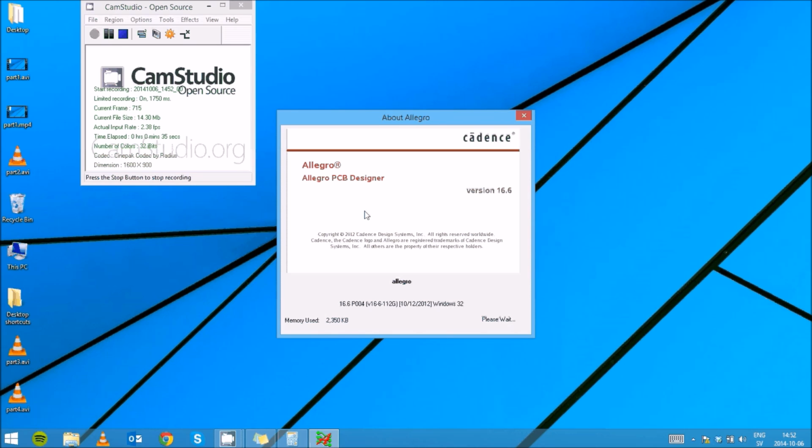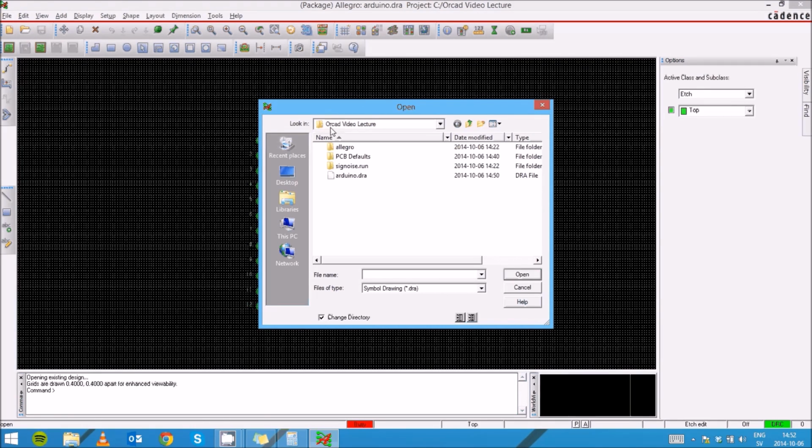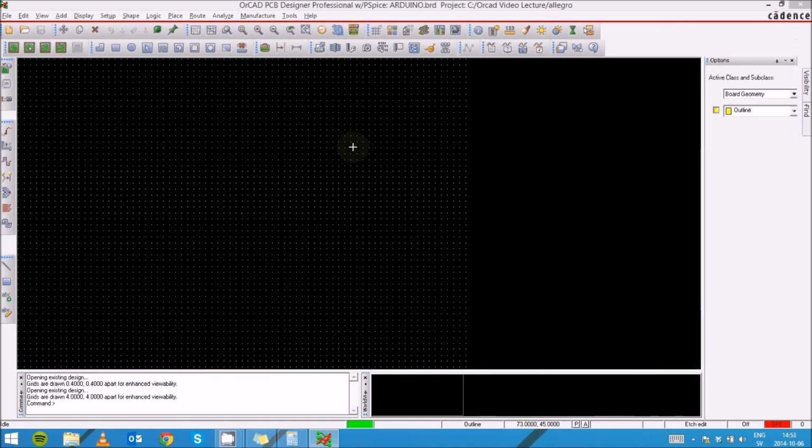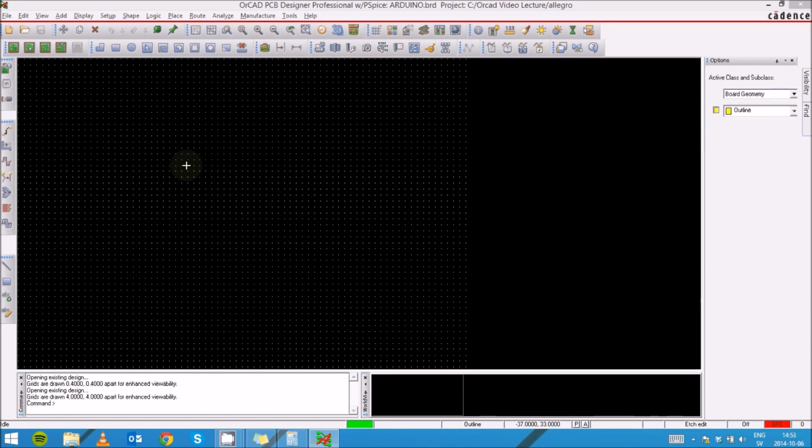We start PCB editor, and then we select open. This is our OrCAD video lecture directory, and we go into Allegro. We select here board, and this is the board that we created earlier, Arduino, and just double click it. So now this board is open. Where are the parts? Here they are.